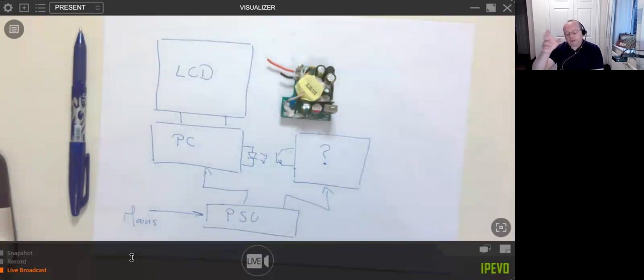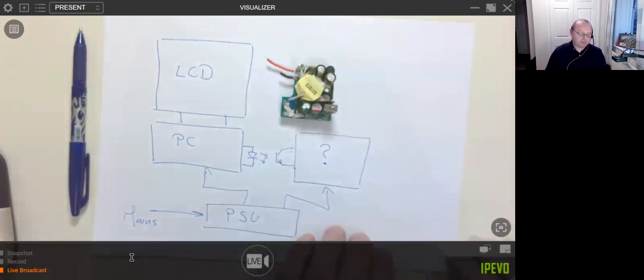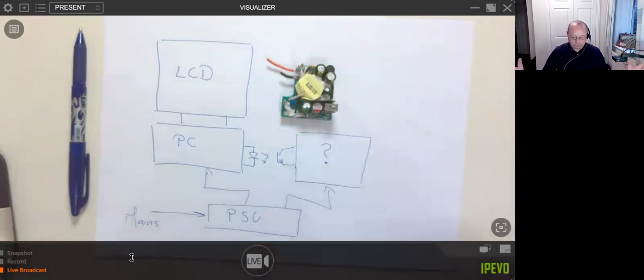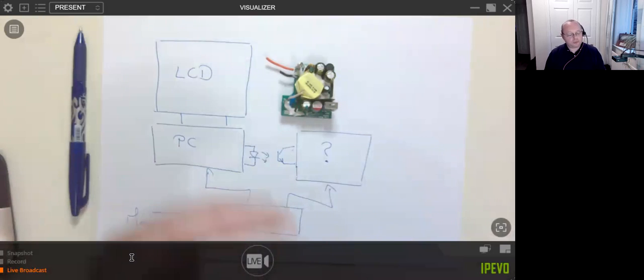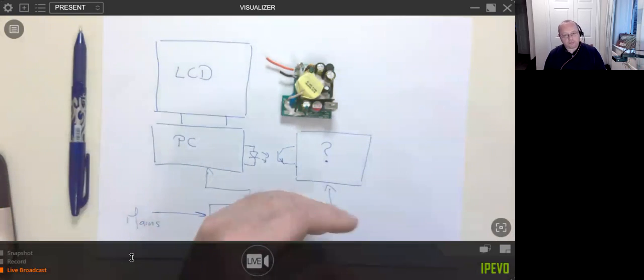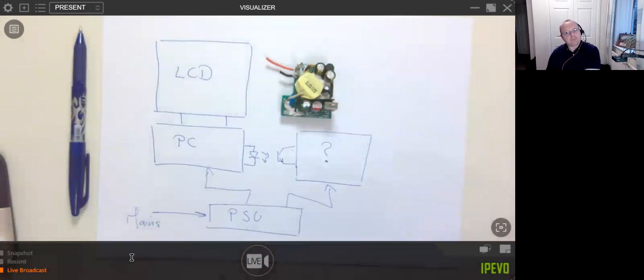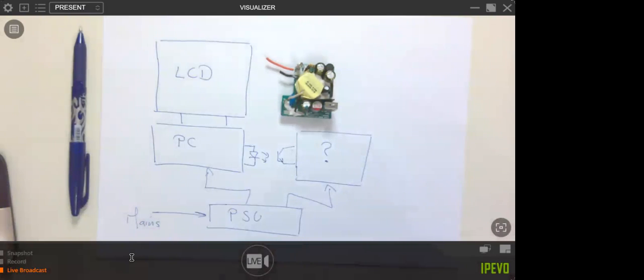So I would, in all honesty, the answer to the question really is pre-compliance. You get a number of different power supplies that look like they stack up on paper. You get your application, whatever it may be, and you take it off to the test site and test a load of them, and work out which ones meet the criteria of not only the standard for safety, but meet the criteria for your application. Yeah, so that's how I would do it.